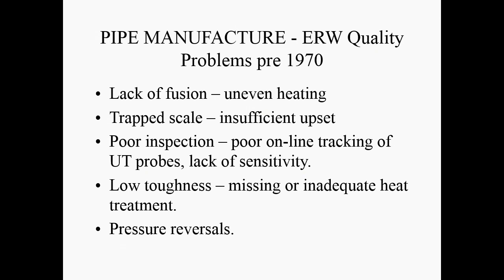When you force things together, you want to squeeze out some of the molten metal, because what that molten metal does is it drags the oxide contamination out with it. And we call that upsetting the material. Doesn't mean making it cry, it means actually plastically deforming the material so that we get that flash. And that takes away some of the rust and the other defects.